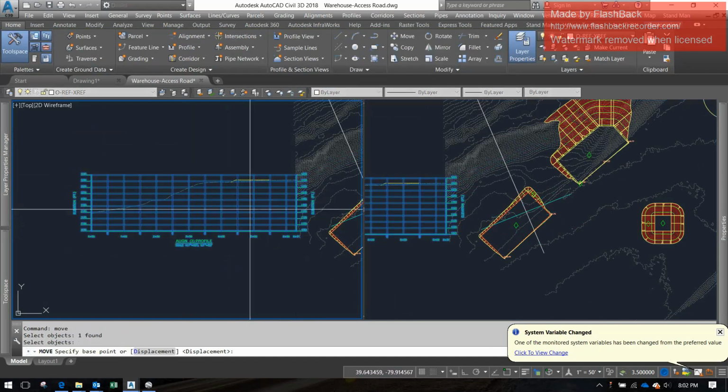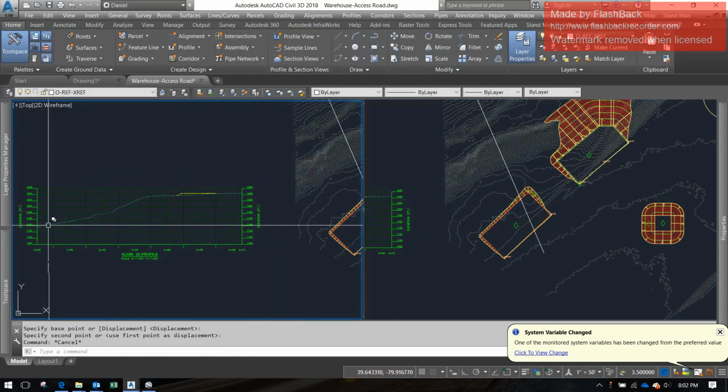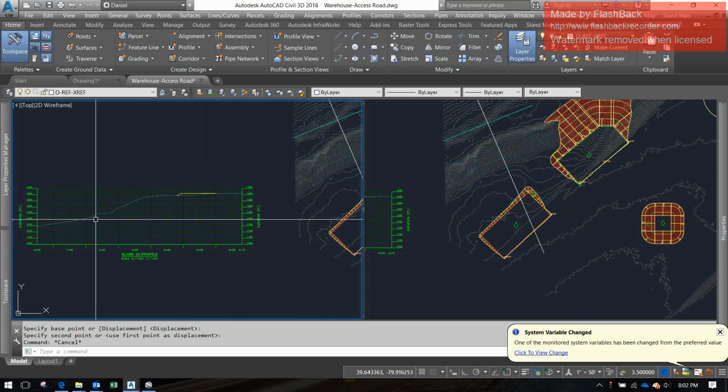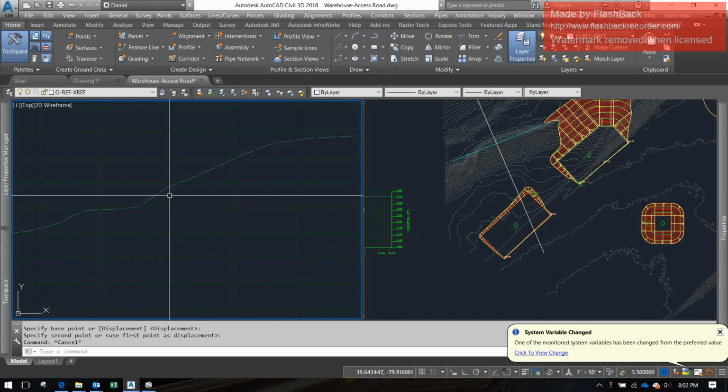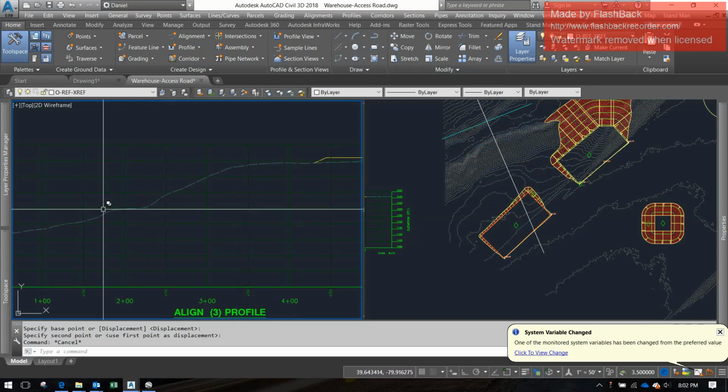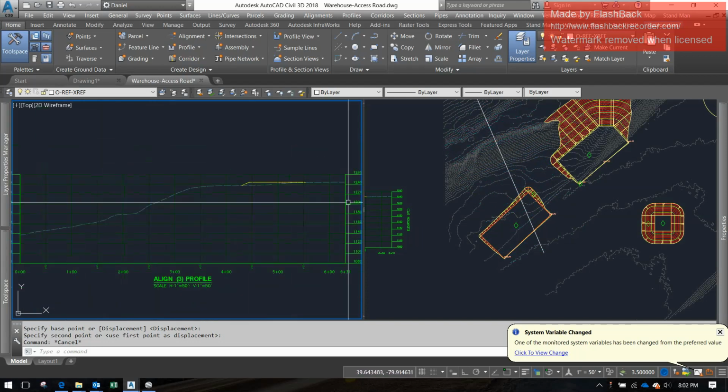So now you'll notice as I move across my profile on the left side of your screen, there's a blue line that advances along the profile line, along this polyline on the right side of our screen, just to kind of indicate where we are on that profile. You'll notice right here where the contours get flat, there's a spot, which I imagine is a bench or something like that, maybe a road, a real wide road where something's allowed to pass.